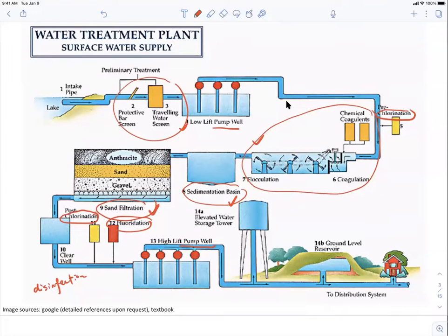Okay. So for chlorination, one thing I want to point out is that normally people will put basically an overdose of the chlorine in the water. Okay, so mainly because we want to make sure that we can have an extra amount of the chlorine to remove potentially more pathogens in the water. Okay, so normally the amount that we want to ensure is that the chlorine level has to be larger than 2 milligram per liter.